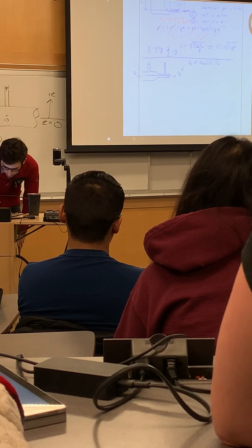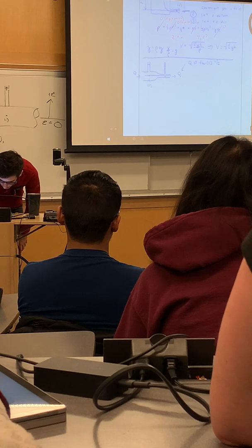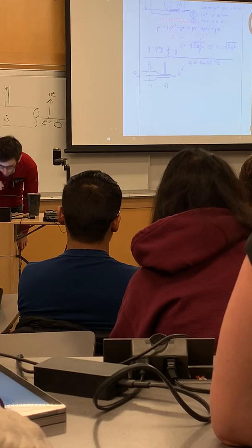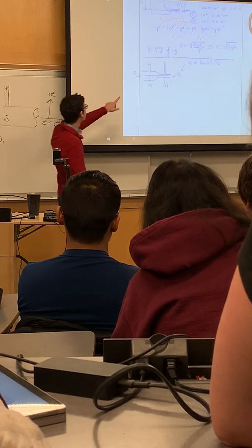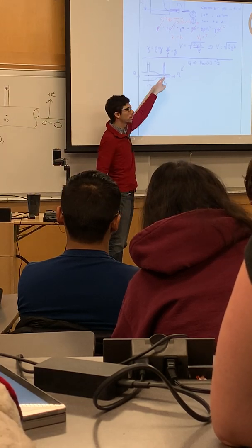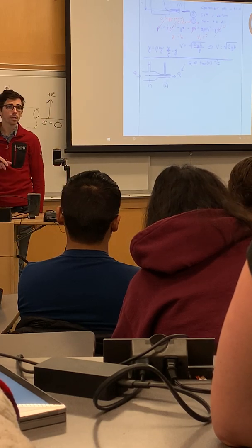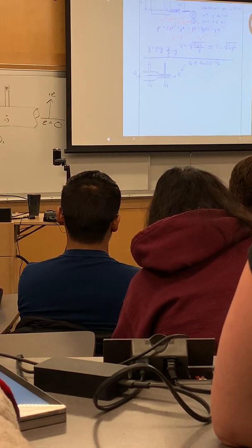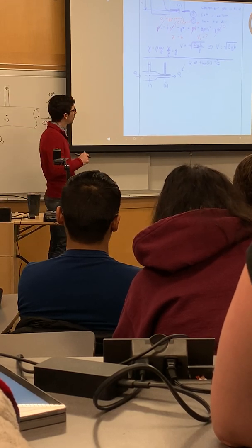Okay. So if we were to apply this, we would probably want to start by dropping a point 1 and dropping a point 2 along that center line, right below those piezometers. And that allows us to take advantage of the fact that we're measuring the static pressure of the fluid at those locations in those piezometers, right?